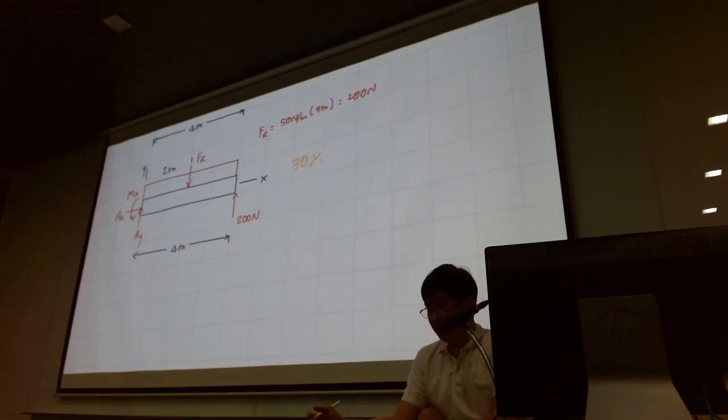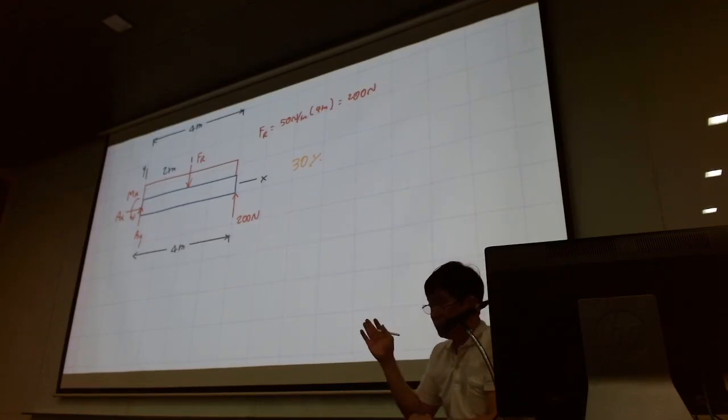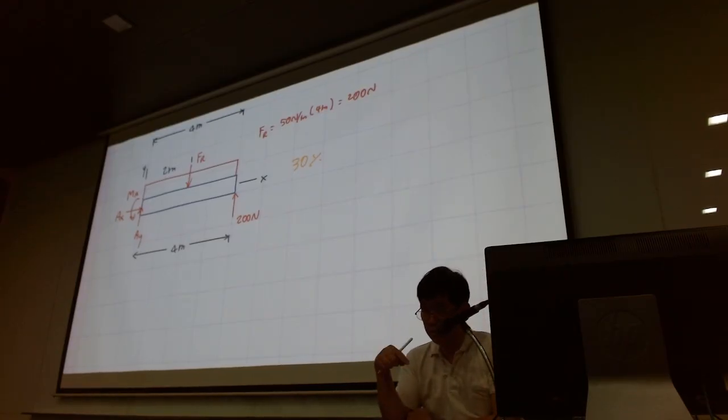Okay, so that was roughly the time that you should be using. So for the free body diagram, just redraw the whole thing. If you have distributed loading, you have to draw the outline of the distributed load without the arrow, and then place the FR at the centroid of the area. I don't know if you have covered that in statics, but we'll go into more detail on how that is done later on as well.